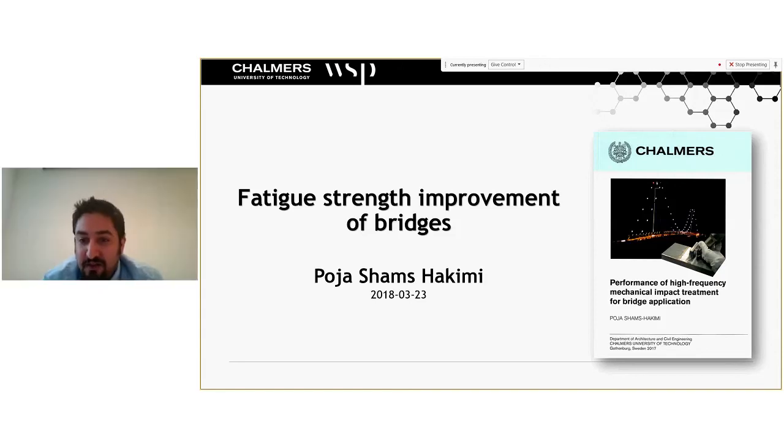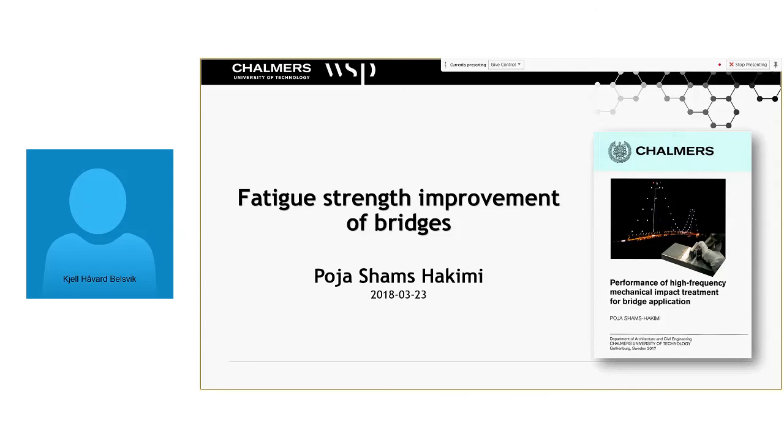These are very interesting numbers and figures, but of course everything is case specific, so you would have to investigate whether these details are suitable for treatment or not. Yes, as we need to have a bridge with standardized sizes, stiffeners and so on, and also standard details, the possibilities to reduce the sizes is possible to do on a general basis, and also then we can use this method that we have seen improves the fatigue strength in the needed areas only.